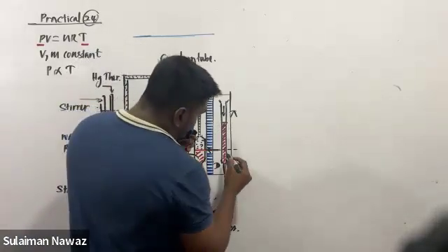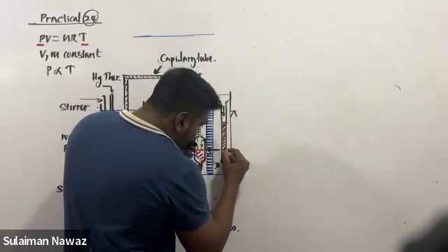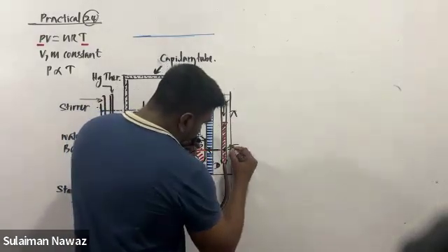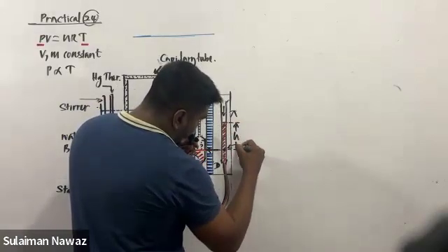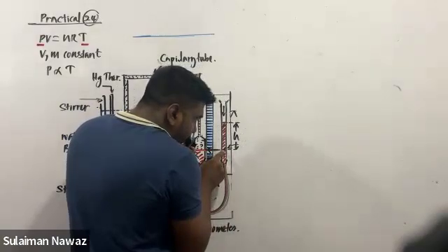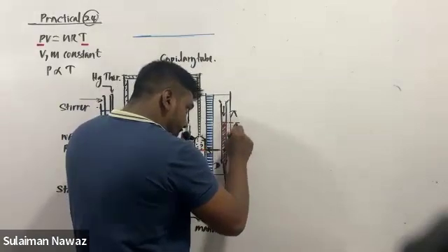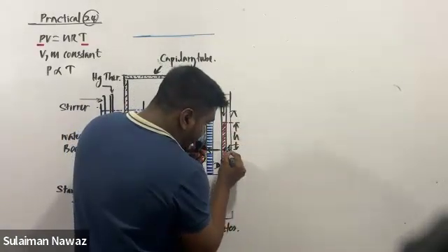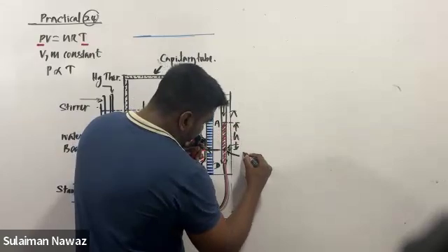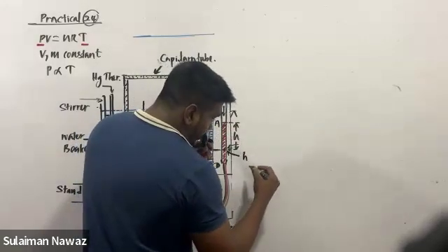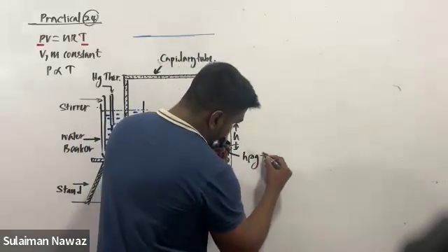If I ask you, what is the total pressure at this point? If you know the height from that point to the free liquid surface, simple H, the total pressure at this point will be H rho g plus P. Am I correct? H rho g plus P.